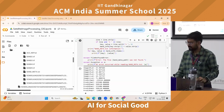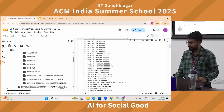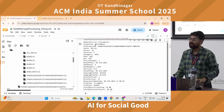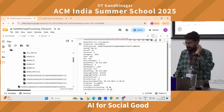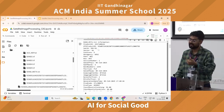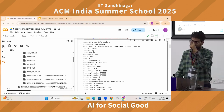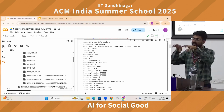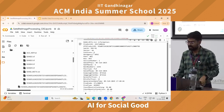Here you can see some of the important parameters. It starts with product ID, satellite ID, Indian Resourcesat satellite R2. So the satellite name is R2. The sensor is AWiFS. The AWiFS sensor basically consists of 4 subscenes A, B, C, D, so it has 4 cameras in it. We are working on subscene D. The generation center is NRSC, then path and row.